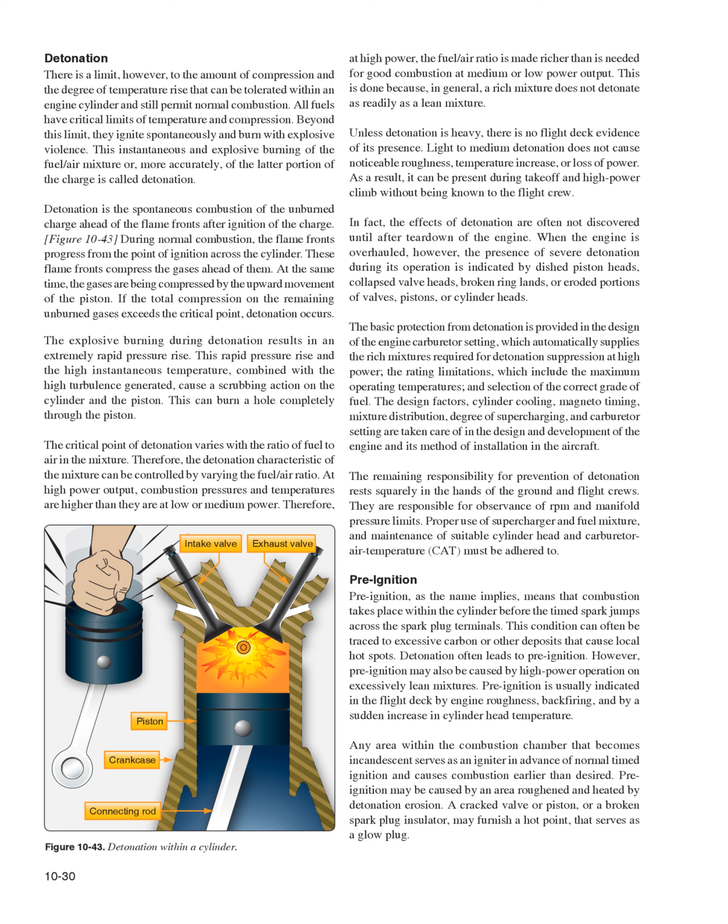Unless detonation is heavy, there is no flight deck evidence of its presence. Light to medium detonation does not cause noticeable roughness, temperature increase, or loss of power. As a result, it can be present during takeoff and high-power climb without being known to the flight crew. In fact, the effects of detonation are often not discovered until after teardown of the engine. When the engine is overhauled, however, the presence of severe detonation during its operation is indicated by dished piston heads, collapsed valve heads, broken ring lands, or eroded portions of valves, pistons, or cylinder heads.